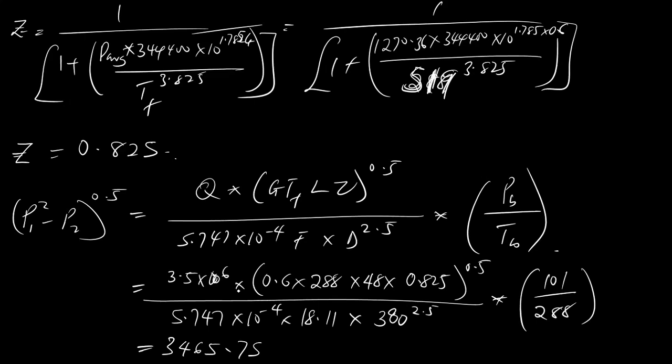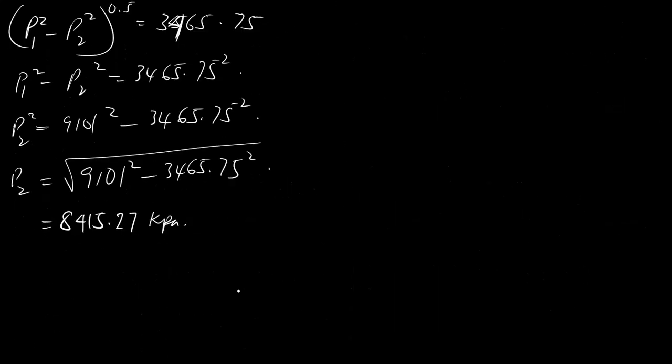All this is constant. There is a correlation with this value here. We now need to go back again and recalculate our Z, the compressibility factor, to see if it's closer to 0.825.